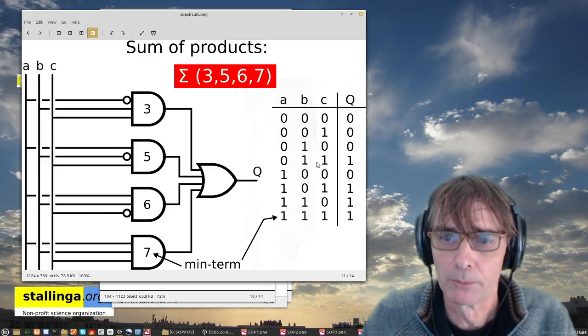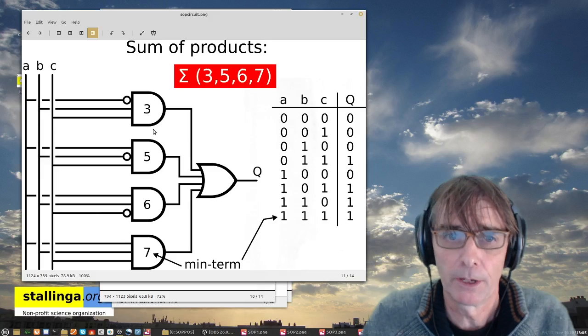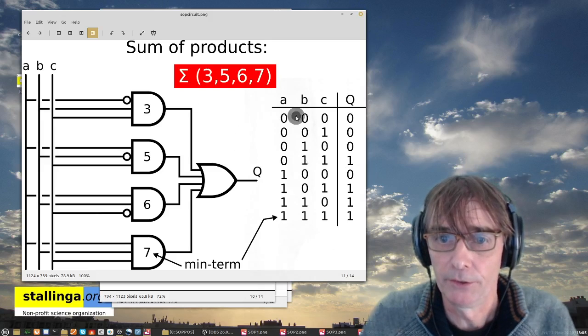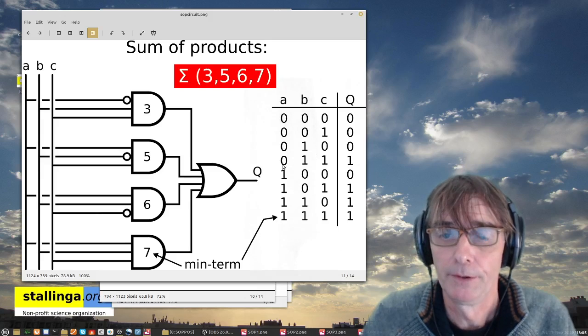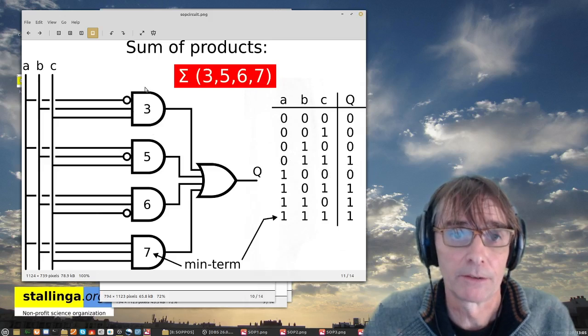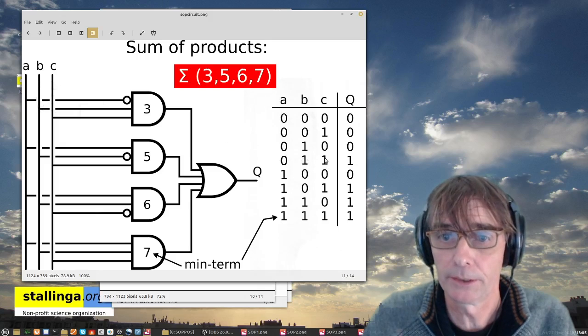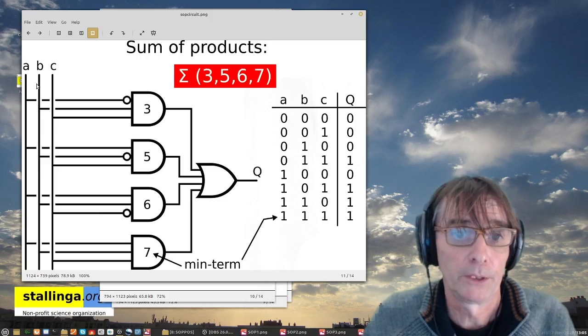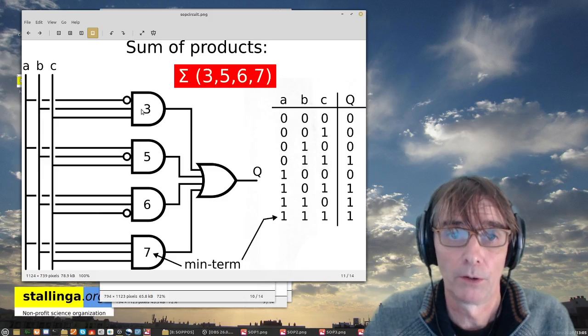If you have this truth table, you just copy every line that you have here and make a gate based on that min term. So for instance, if you take the 3rd line, this is 0, 1, 2, 3, the 3rd line, this line corresponds to this AND gate where A is inverted because it has a 0 here, B comes directly, and C comes directly, and then we get this. Of course, this line will be 1 for this combination 0, 1, 1 at this gate.